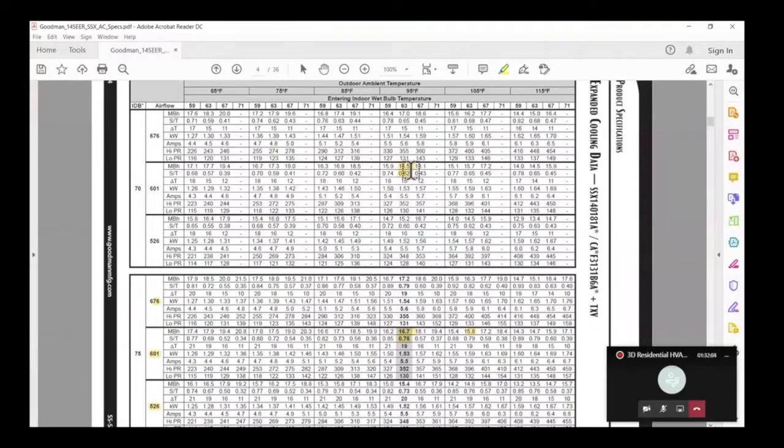It is a good time right now. Let me just finish a couple points on here really quick. So we talked about making it hotter outside. Now, what I didn't mention, when you make it cooler inside, remember our load calc was based on that number, 75. And if we suddenly say, well, we want it to be 70 inside, that changes the delta T. We'd have to go back to our load calcs and change the indoor temperature to 70. And then guess what? Our delta T changes, our loads go way, way higher because we've reduced the indoor temperature by 5 degrees. So you don't want to do that. But I just wanted to illustrate what happens.